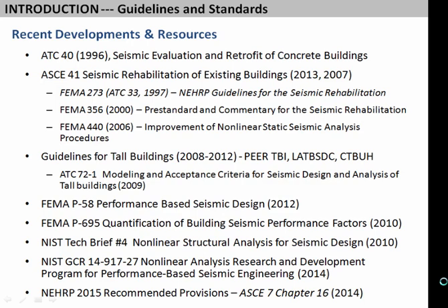I listed all these documents here. I'm not going to talk about all of them, but as Ron talked about this morning, one of the landmarks for getting nonlinear analysis thinking into practice was the FEMA 273 in 1997, which in its modern version is ASCE 41. So that's one of the documents that I'll be referring to as I go through today. Also, the tall building documents we've been hearing about, and in particular this document ATC 72, Modeling and Acceptance Criteria. There's also been a NIST tech brief that I was involved with that put together some other guidance on nonlinear analysis, and things are continuing.